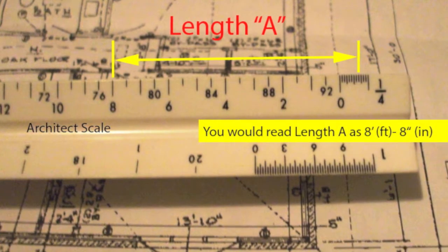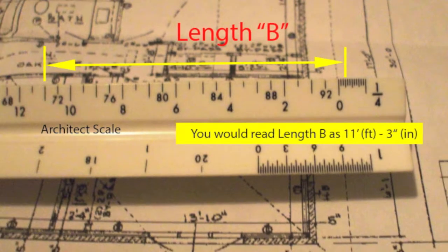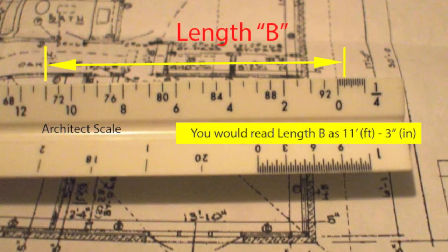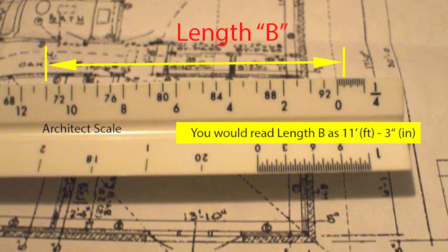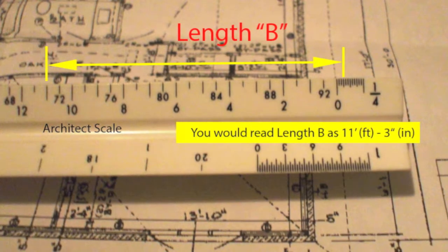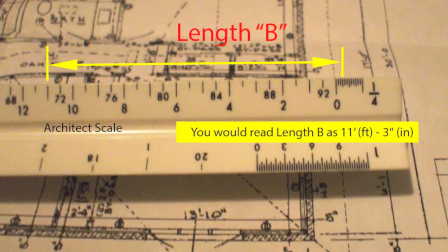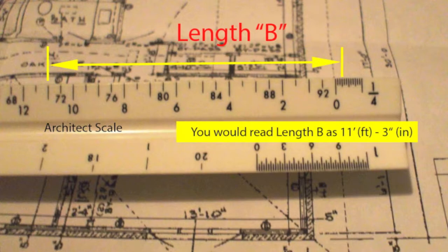Now, let's try a different length with the same scale. Length B starts on the number 11. So you read it from 0 to the left as 6 inches, 1 foot, 1 foot 6 inches, and so forth to 11 feet in length. The line ends on the 3rd tick mark or graduation from 0 to the right.